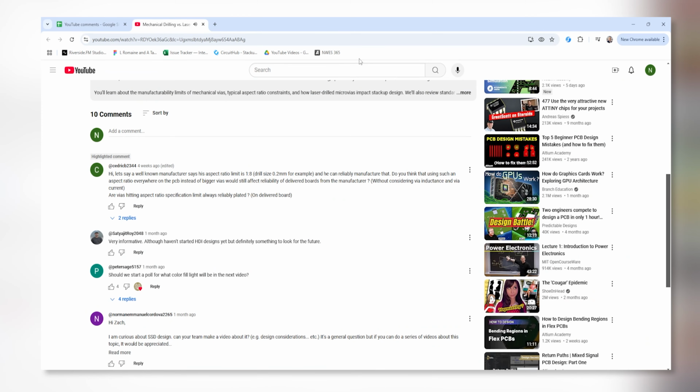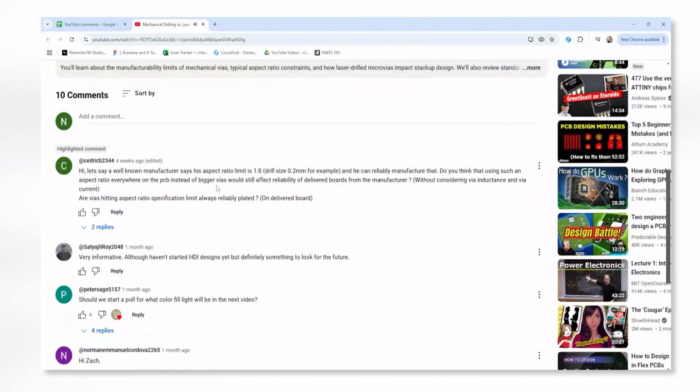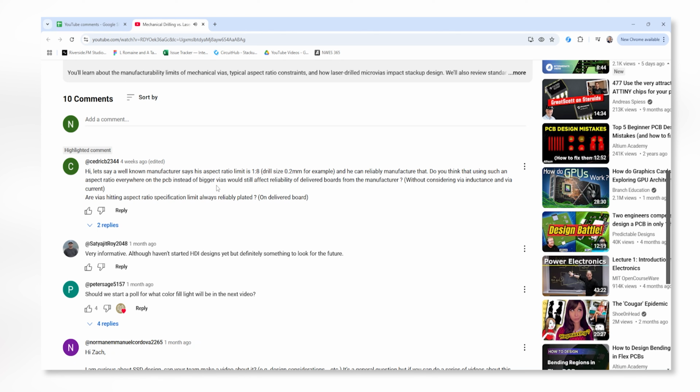This last question comes to us from the mechanical drilling versus laser drilling video. Cedric B asks, hi, let's say a well-known manufacturer says his aspect ratio limit is 1:8. You would actually say that as 8:1 because it's the depth to diameter ratio. And he can reliably manufacture that. Do you think that using such an aspect ratio everywhere on the PCB instead of bigger vias would still affect reliability of the delivered boards from the manufacturer? So this is a really good question.